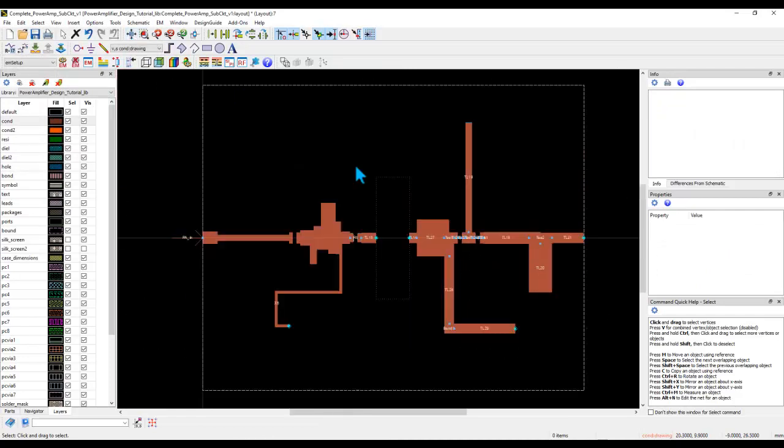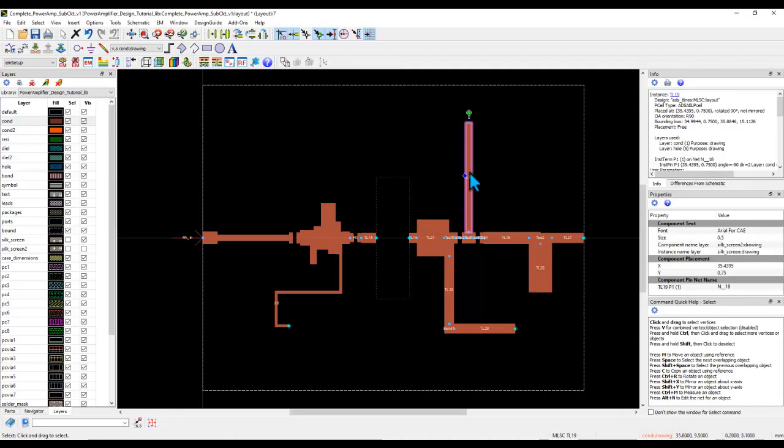So the choice is yours. Now, once I have it here, I also have this long short circuit stub, which is actually occupying a lot of area here. And here I would like to do some ground pouring. I would like to write my text on the PCB, my name, circuit name, and all that. So we can even bend that.